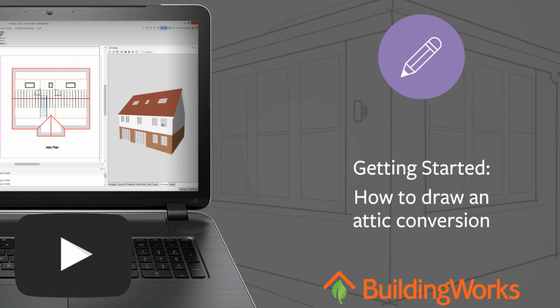In this video, we demonstrate how to draw an attic conversion to an existing property. To draw and estimate an attic conversion, you first need to draw the existing property. You can then copy the first floor level to create a new attic level. Select the attic conversion option from the attic drop-down menu to draw the existing roof.